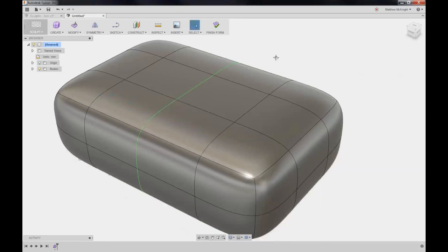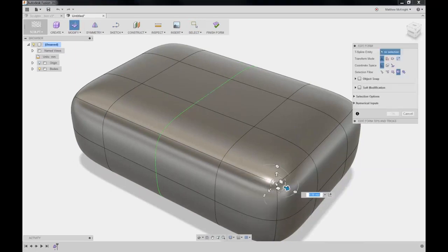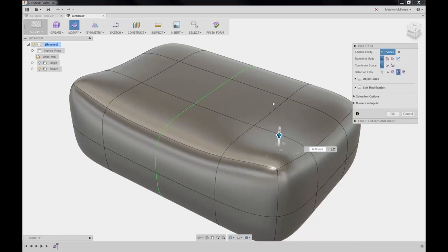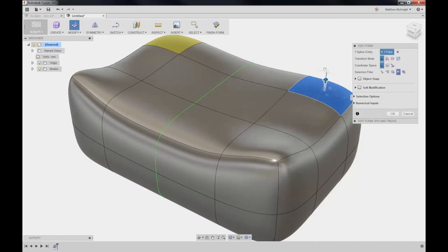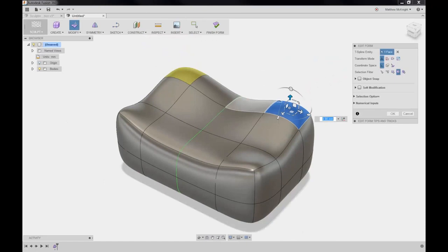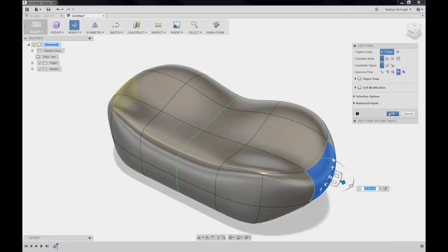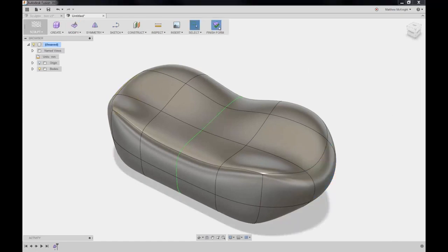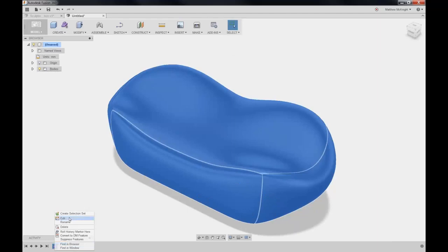And subsequently, if I then use that symmetry, you'll note that now in using the move or modify manipulator, if I'm making a change to one side of my geometry, I'm automatically making a change to the other side as well. So this will help you if you're making symmetrical objects and you're modeling both halves in one go, as the ability to manipulate your geometry on both sides equally. Okay, again, exiting the form will then bring us back into the environment. Again, I'm just going to repeat on some of these things.